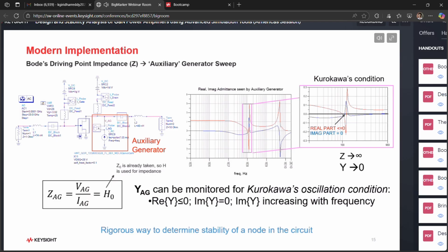So that essentially brings me to the simple, effective approach for stability here, which is: look at the intrinsics, use a rigorous technique, NDF or driving point at minimum, and see if your circuit's stable. If it is, consider all the loads. If it's not, look for loops. And that's the way to move forward. The problem here is that the setup is way too complex.